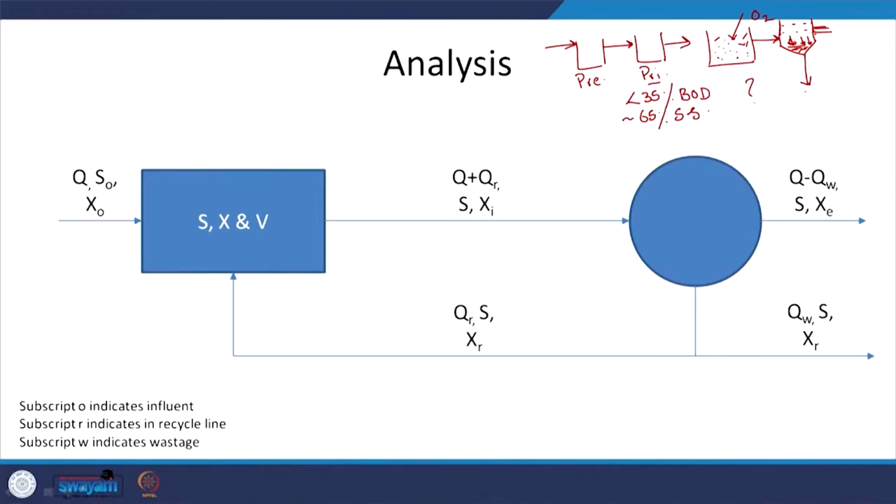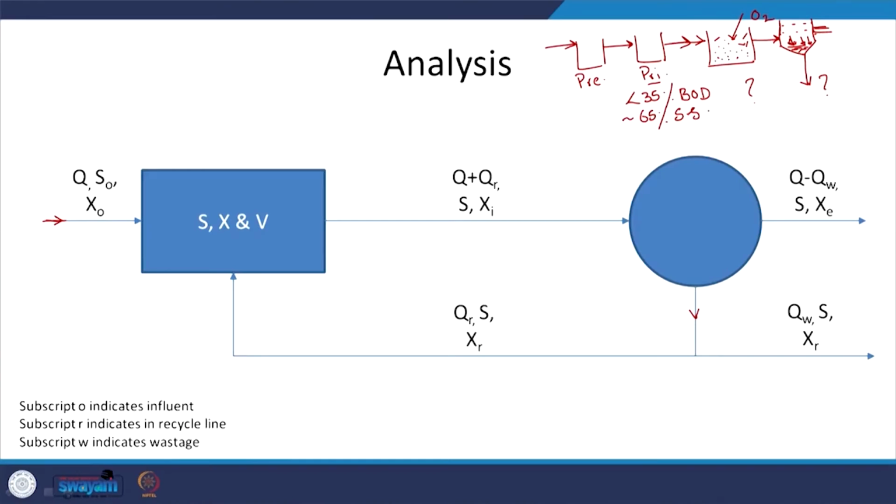So, you are going to have to stabilize it or degrade it into more stable compounds, but we do not always waste it. For example, this is the waste, we do not always waste it. Why is that? Here in our sewage or in our waste, we have some microorganisms, but the kind of microorganisms that lead to the degradation of our waste are not typically present. What microorganisms are present here? We do have microorganisms coming in, but they are enteric microorganisms which are not going to assist in degrading our waste. So, where will the source of microorganisms be within this aeration tank?